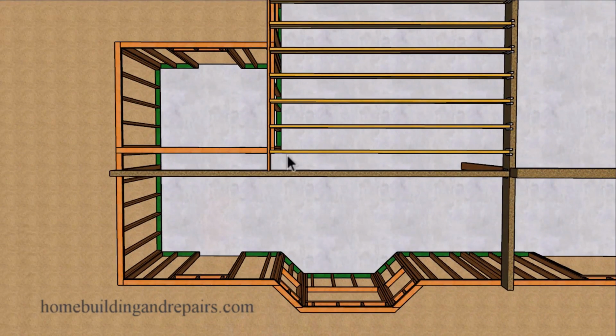And another thing I want to point out is that if I moved this wall over, I could make the beam shorter and probably go with a smaller beam if that would work for your particular project. And of course, this beam does need to be in this location to work structurally with the roof. So you're probably not going to have a choice of moving the beam back.